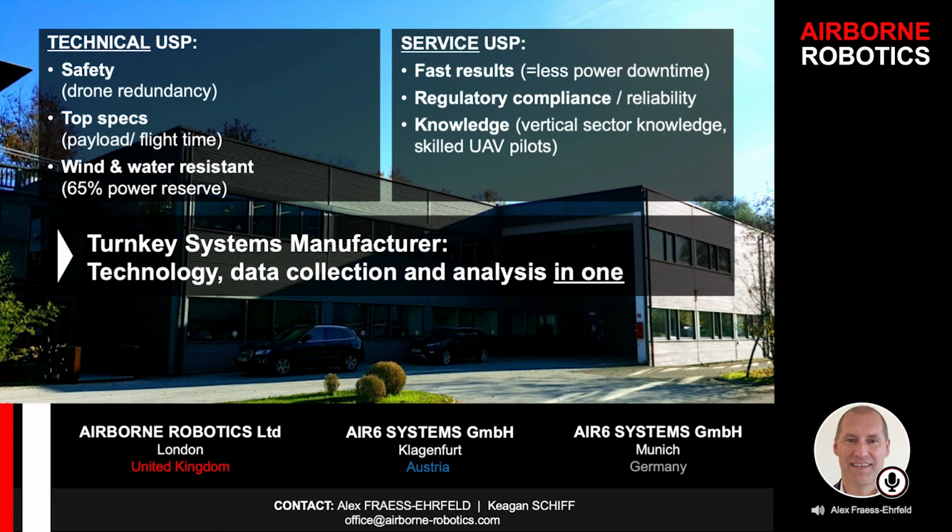Rob, why don't I hand over to you, because you're much more of an expert on it, so maybe there's something to add. Yeah, look, I guess I won't add too much, but the photogrammetry process on its own produces point clouds in order to align all the photos. So you'd need at least a sparse point cloud to do photogrammetry. Then you typically produce a dense point cloud before you create an orthophoto and a terrain model. So you'll get point clouds from photogrammetry, but if we're talking about LiDAR plus photogrammetry, then there's a lot of different levels that it can come together.